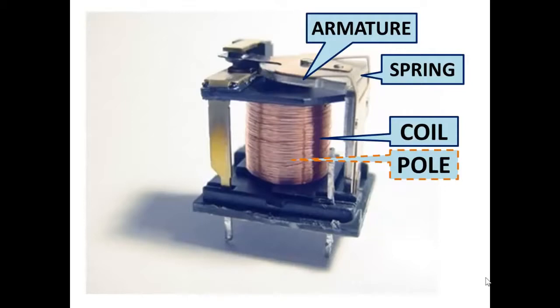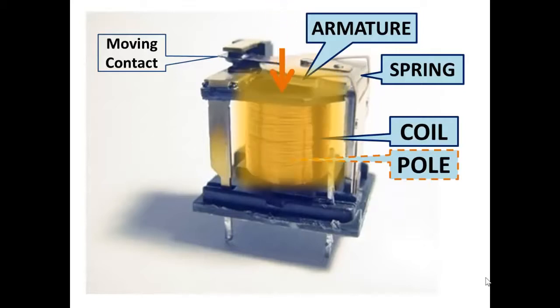Attached to the armature, as you see, the armature is suspended on a spring, and on the opposite side of the armature from the spring you have a moving contact. The moving contact travel is restricted in each direction by stationary contacts. When current flows through the coil, the armature is drawn to the pole piece of the coil against the tension of the spring. As the armature travels towards the coil, the moving contact travels as well.